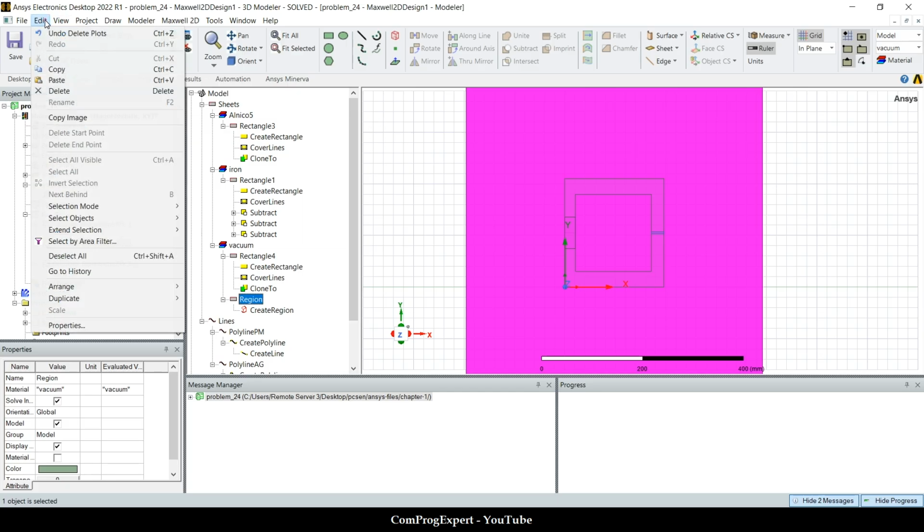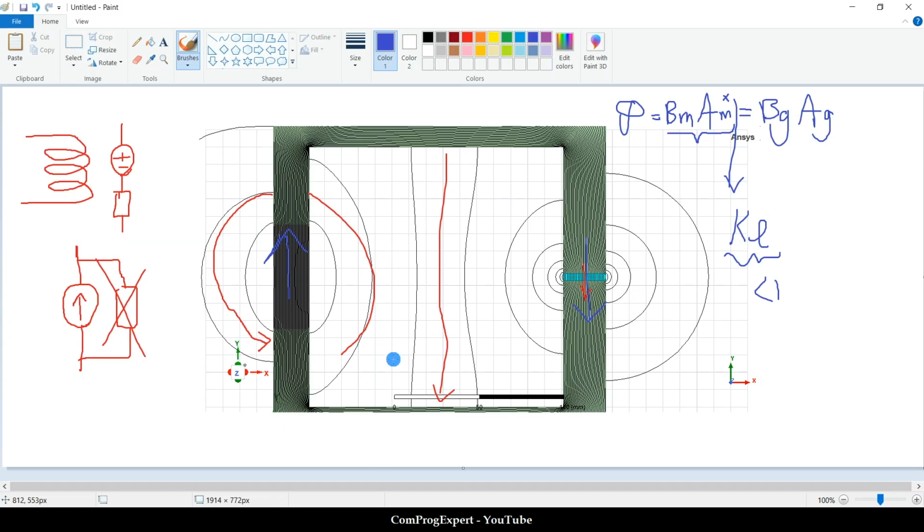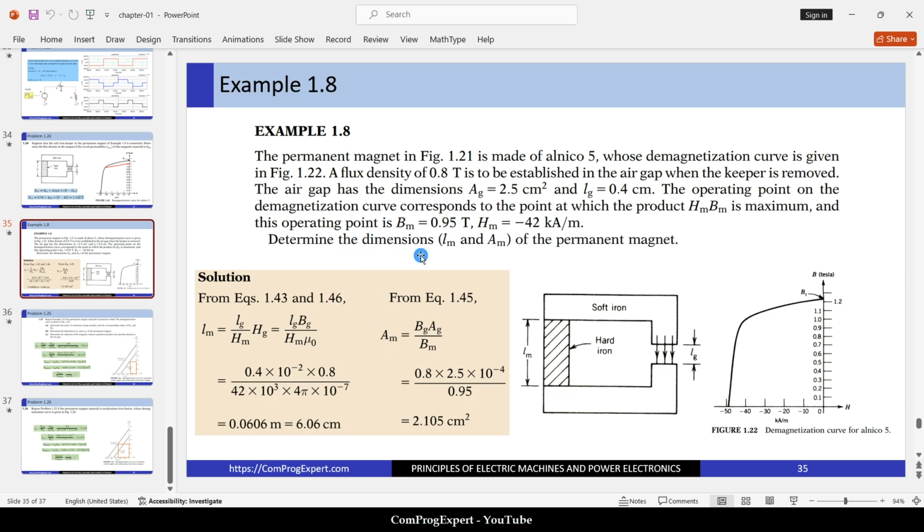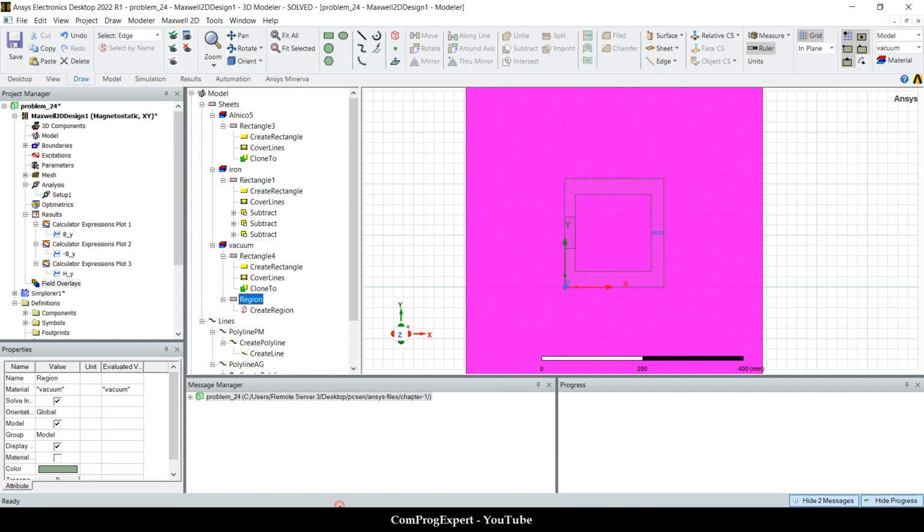And I am going to consider the relative permeability of the region equal to a very low number, close to 0, to suppose that we don't have magnetic flux lines in the region, right? A fictitious material. Just to consider this perfect assumption that we have here, that the total flux generated by the magnet is passing through the air gap.